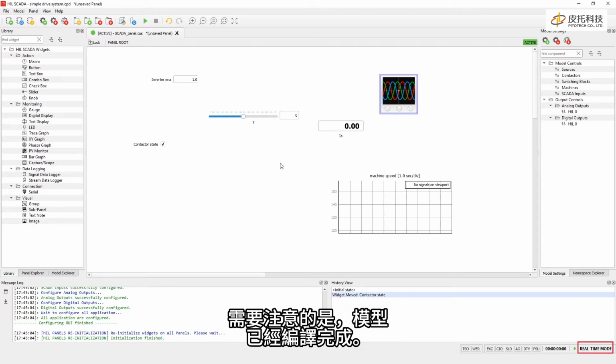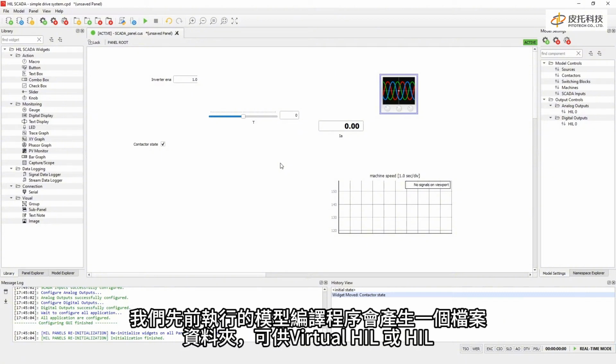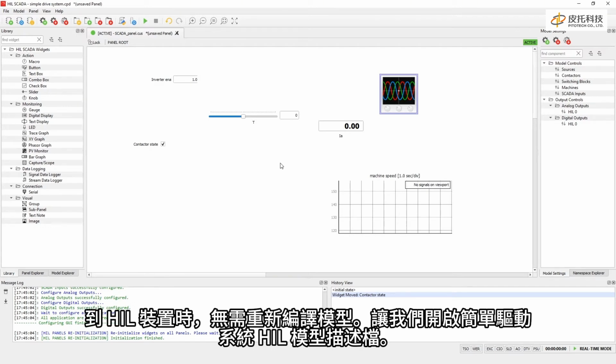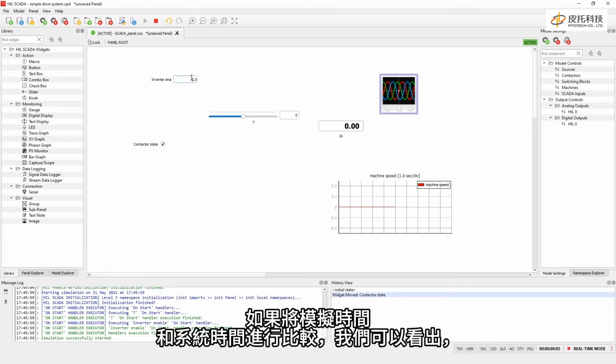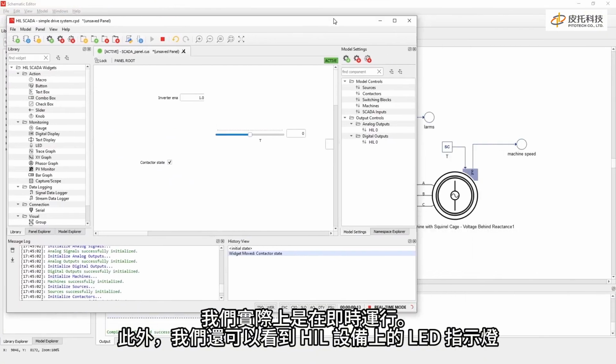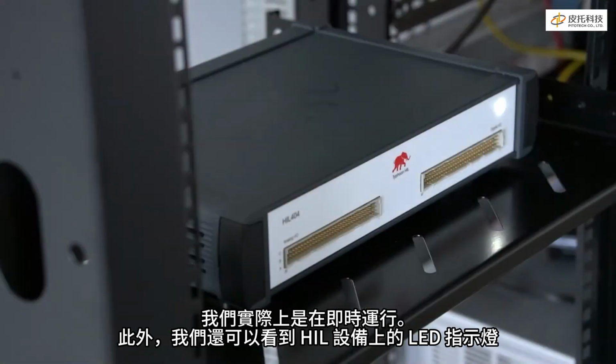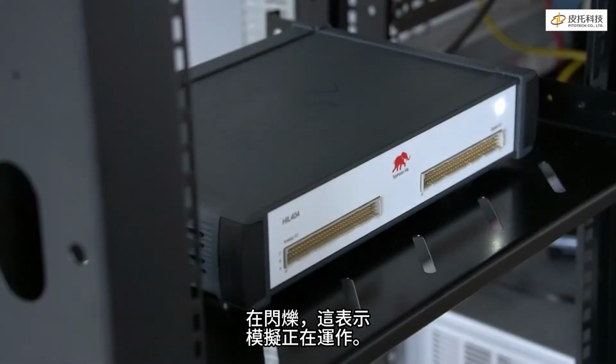It is important to note that the model is already compiled. The model compilation process we performed earlier generates a file folder which can be used by Virtual HIL or a HIL device. This means there is no need to compile the model again when switching from Virtual HIL to a HIL device. If we compare the simulation time and system time, we can see that we are really in real time. Also, we can see that the LED on the HIL device is blinking, which means that the simulation is running.